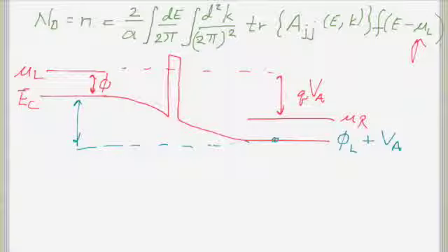And this is a simple case. If the dopants are different, then there'll be an extra potential over here, because the difference in the Fermi levels is fixed, but if the dopants are different here, then I'm going to have an extra potential drop, like in a PN junction, right? In a PN junction, your Fermi level is flat, but there's a big change in the potential as I go from one side to the other.